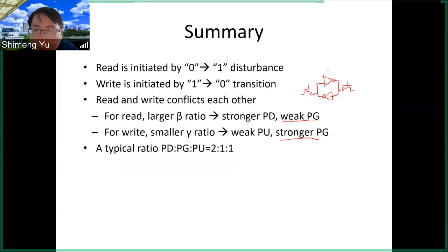So this latch in the middle is where you store the data. This is the memory state. That is a stable circuit. Then the read operation. So basically you want to provide a bridge between the internal states that you store here to the external outside world. So then you just want to have a weak link here to detect what's inside.